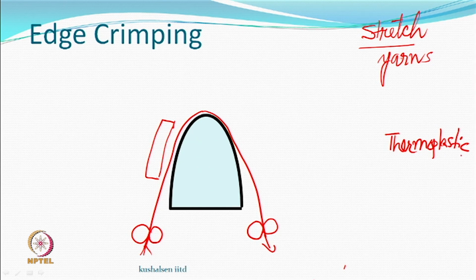It is also a thermoplastic yarn. So, you can put, let us say, a heating device as moving. Alternately, you can heat the edge also, but maybe it is easier to put a heating device. So, you have a yarn which has been heated to a certain degree, which is sufficient for it to respond, goes over the edge and comes out. And you say, here we are starting with a yarn which is untextured, and here we are coming out with a yarn which is called textured. Not only textured, but I say it is a stretch yarn.